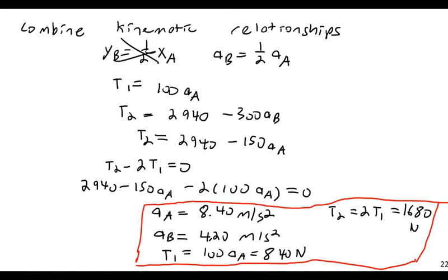Then, for each of my objects, I set up a free body diagram and a kinetic force diagram, where I show the inertial forces on each of the blocks or objects, whatever they are. And then I continue through setting up equations of Newton's second law in the x and y direction, and then you work through it from there.